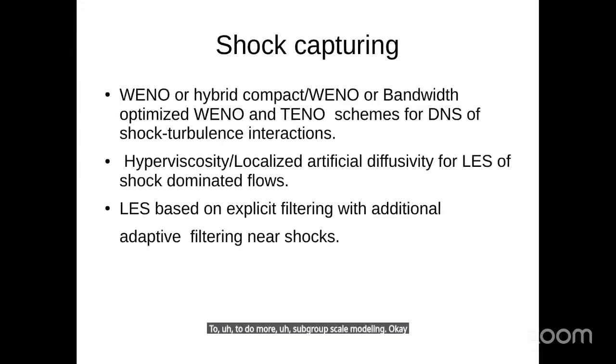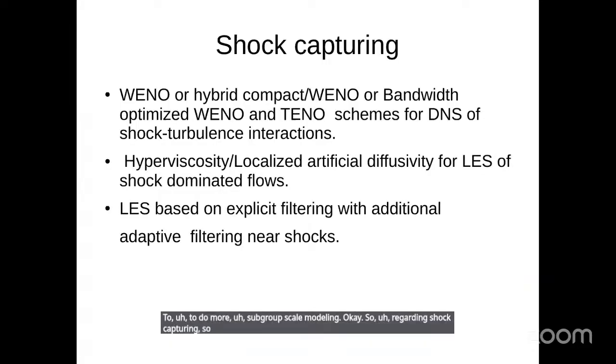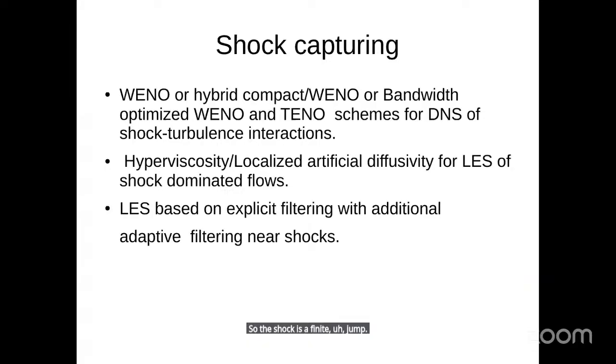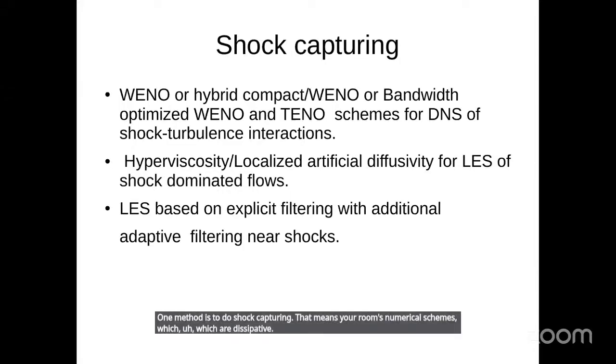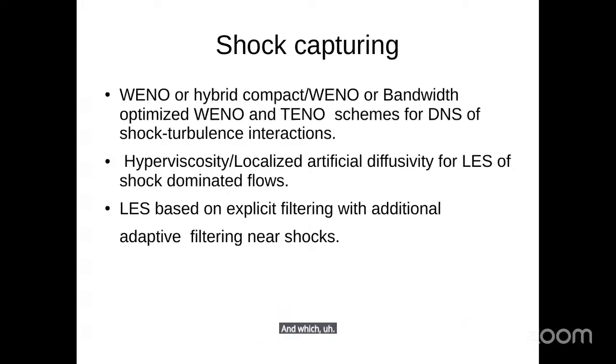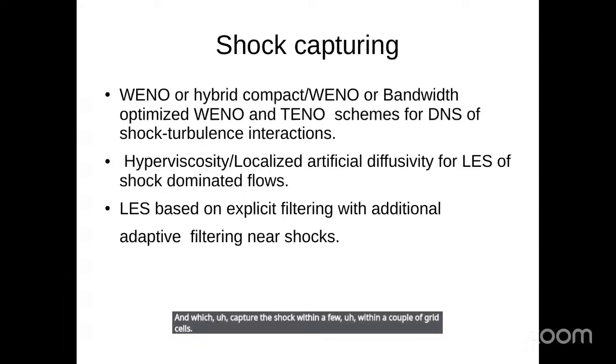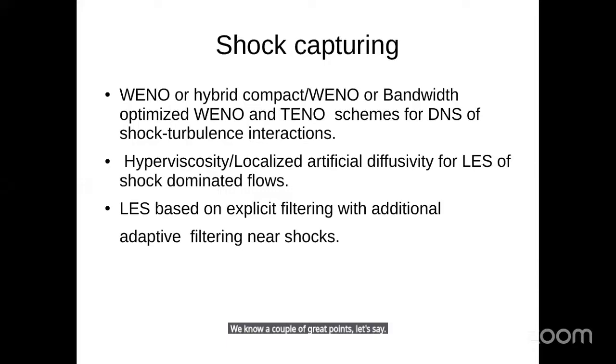Okay. So regarding shock capturing, shock capturing is required. When you have a shock in a turbulent flow, the shock is a finite jump over a very small length scale. Okay. So to capture this, or to keep this in the simulations, one method is to do shock capturing. That means you use numerical schemes which are dissipative and which capture the shock within a couple of grid cells, within a couple of grid points, let's say. So there are different methods which are used for that.